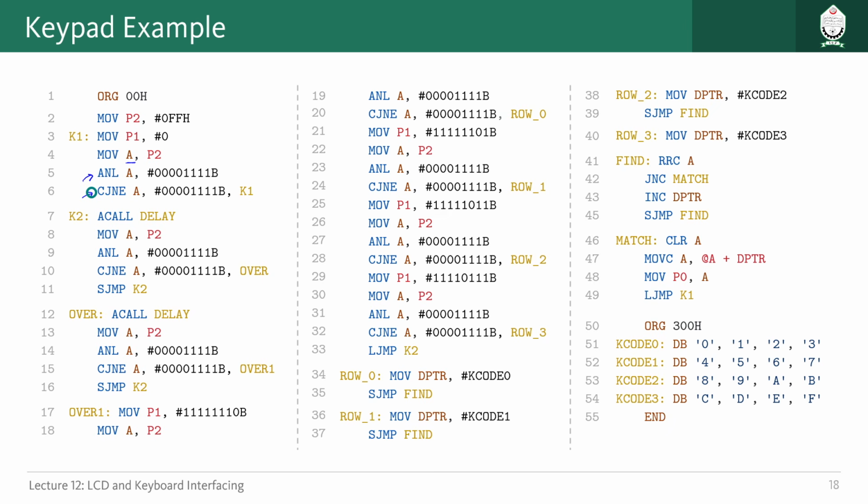So after executing the code which represents that key press, obviously it has to return to the initial position, right? It cannot just do the same thing again, because it has to wait for that key to be released to look for a new key to be pressed. That's why we have this portion for that.